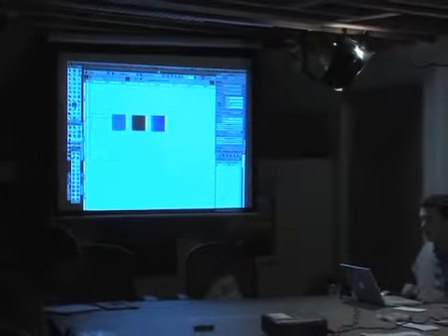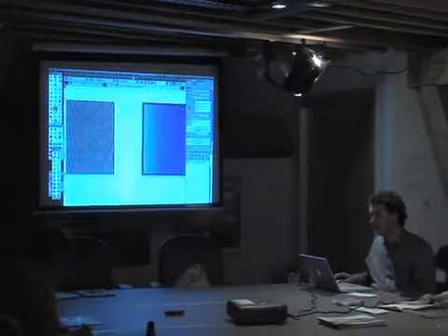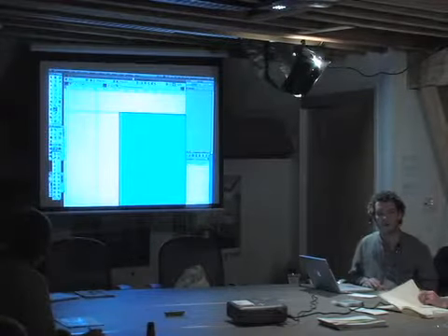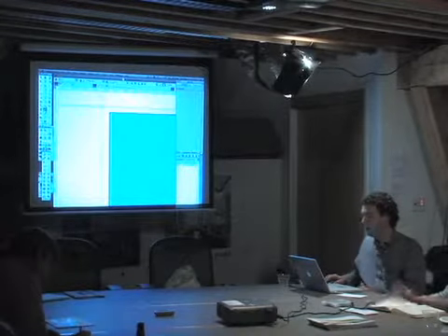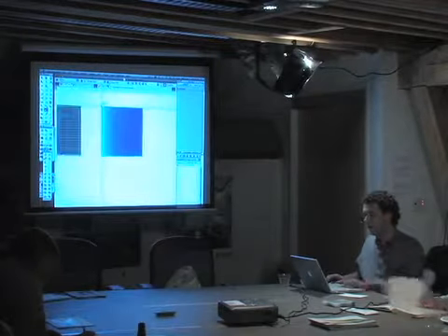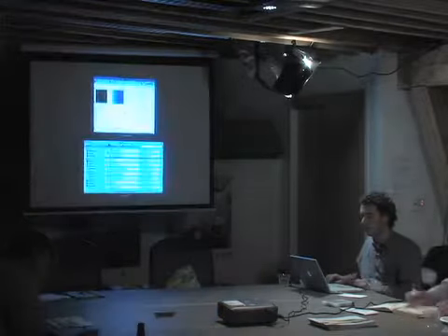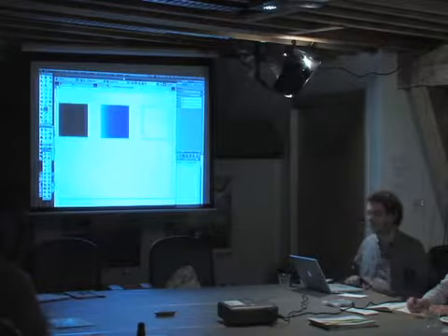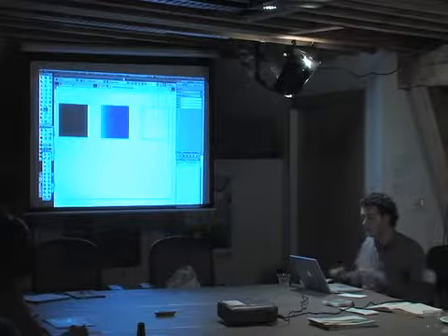This second object is a polyline. The only reason it's a polyline is because I chamfered this corner just ever so slightly. So anytime a polygon has a curve added to it, it becomes a polyline. Any objects with curves to them become polylines. And then this third object is an extrude, and it loses its fill in the 2D orientation.